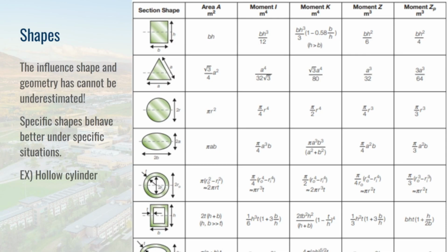For chassis, which is what I did a lot of, I was dealing with round tubes and square tubes. Round tubes are great for compressive and tension forces along their axes. Square tubes can also handle it, but what they can handle better is compressive forces on their faces as well, which makes them great for things you mount to them, like the front bulkhead where the attenuator is. Those forces are translated onto the faces of those tubes. When those tubes are square tubes, they can handle more.